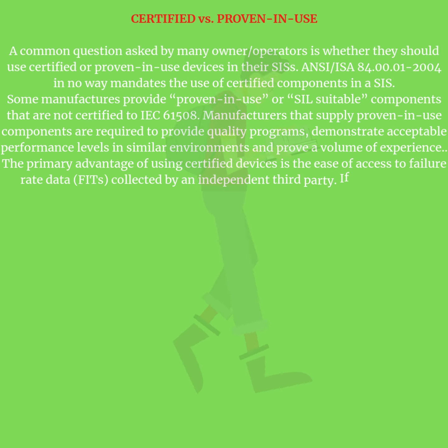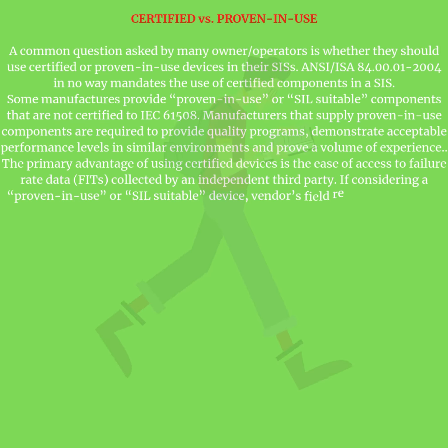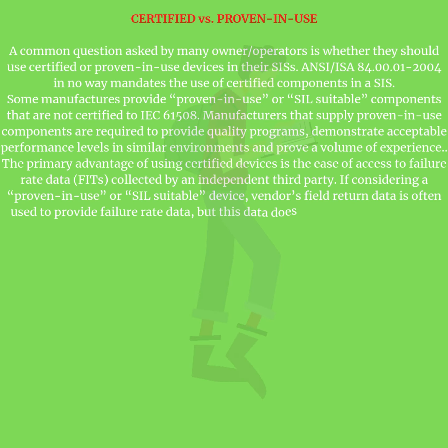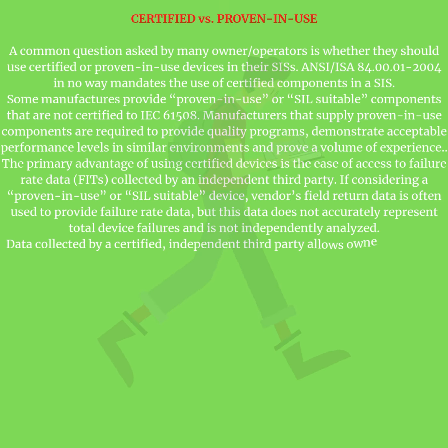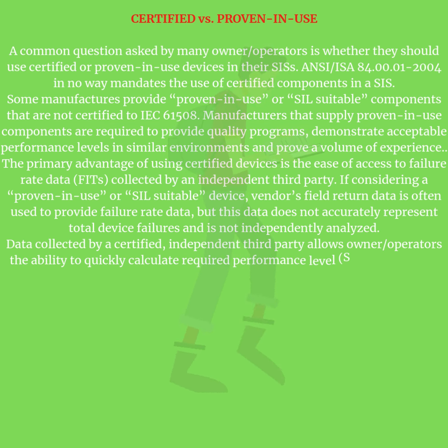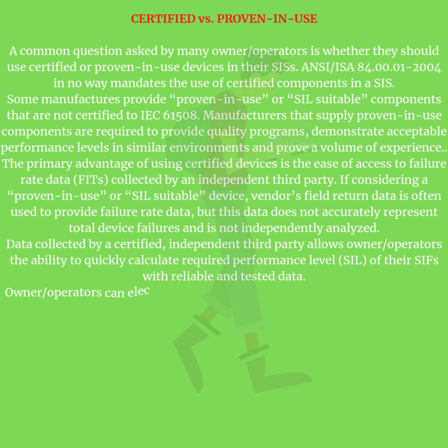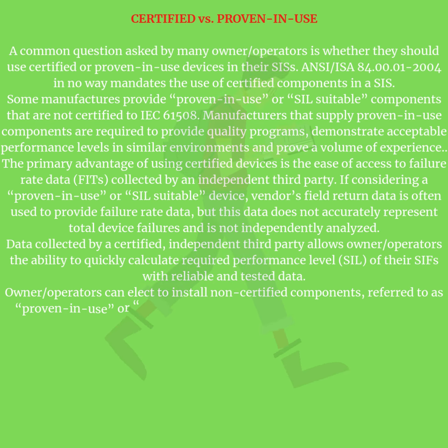The primary advantage of using certified devices is the ease of access to failure rate data, FITs, collected by an independent third party. If considering a proven in-use or SIL suitable device, vendors' field return data is often used to provide failure rate data, but this data does not accurately represent total device failures and is not independently analyzed. Data collected by a certified, independent third party allows owner/operators the ability to quickly calculate the required performance level, SIL, of their SIFs with reliable and tested data.